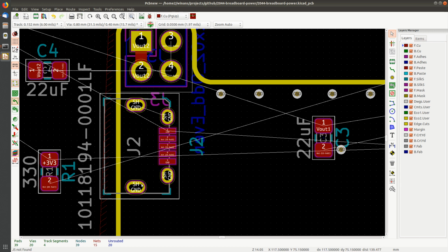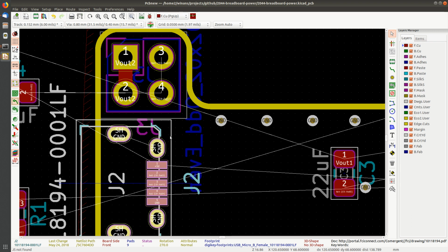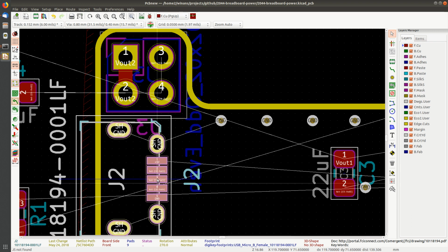These have holes in here, but the pins that go in these holes are only for registration. They don't actually go all the way through the board, so they're not going to hit anything underneath. If the plastic housing of this reaches down underneath here, you're okay. At the moment, I'm not even overlapping the courtyard lines, these white lines. Let's go ahead and do that to minimize the size of this as much as possible.